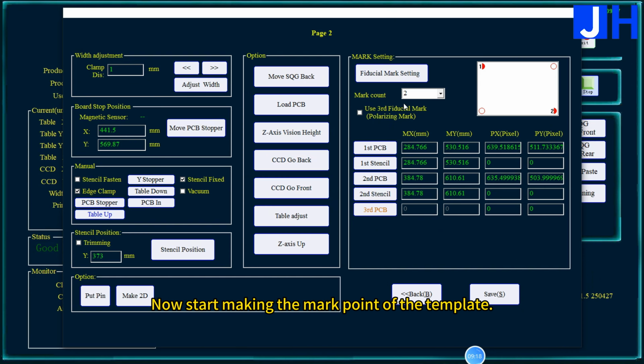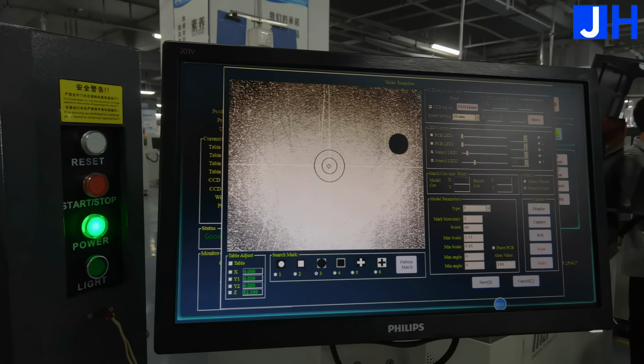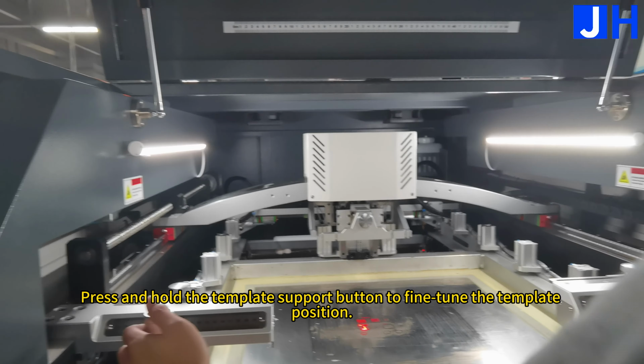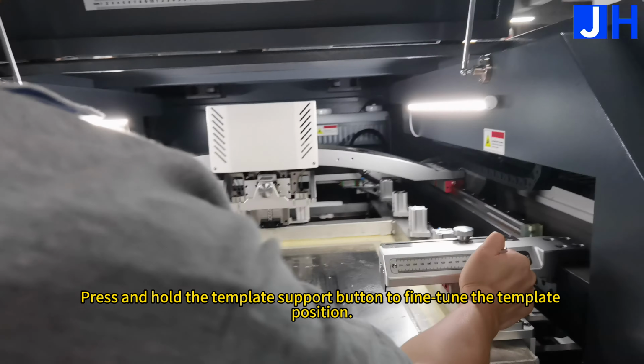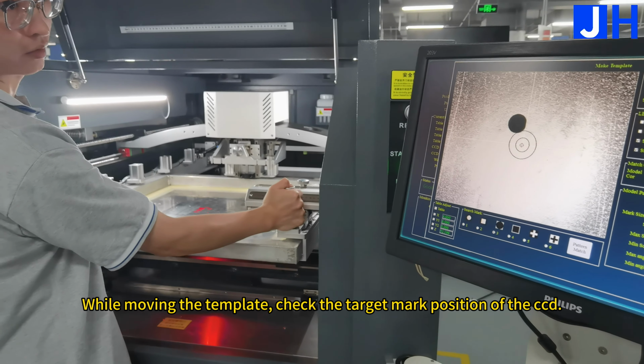Now start making the marking points of the template. Click to enter the template tag settings. The actual template markers are offset from the target points. We need to move the template to the marked point of the target. Press and hold the template support button to fine-tune the template position. While moving the template, check the target mark position of the CCD.